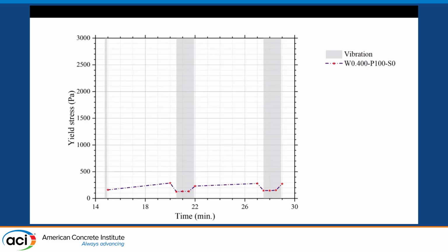Now, what is the effect of aggregate content on the rheology? So this is pure cement paste. In my setup, I was getting about 200 Pascal when it was not being vibrated, about 100 Pascal when it was being vibrated. Next, the 3 lines that just showed up have paste of 85% and 3 different aggregate ranges. Either completely sand or completely limestone chip. It's a weird thing, but the other extreme, and somewhere in between, 50% sand, 50% chip.